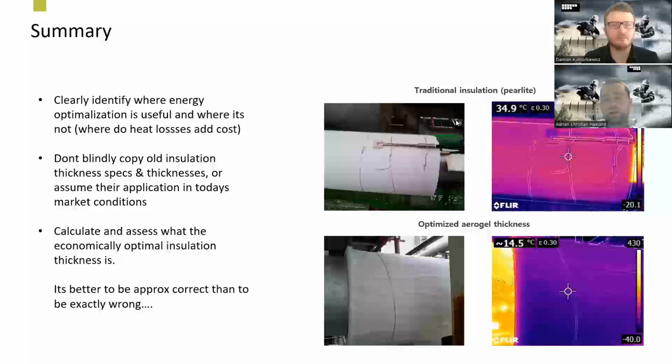Most of the time the cladding will be damaged and water will get in. If you have a water repellent aerogel, maybe you can assume 5 years more, but yeah, it's usually not the insulation material itself that has run out of lifetime. It's usually damage to the insulation and water ingress that destroys the system. Okay, thank you very much for the response.